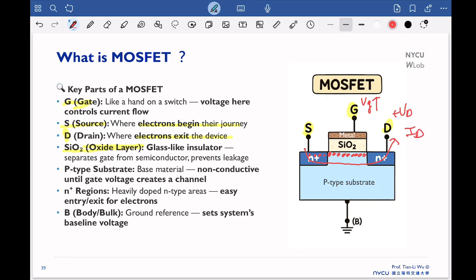And then imagine, as I said, the critical electrical result we are interested in is the drain current versus the gate bias. Most of the time, we put the source grounded to simplify the case here. So we are interested in the characteristic of gate bias versus drain current.